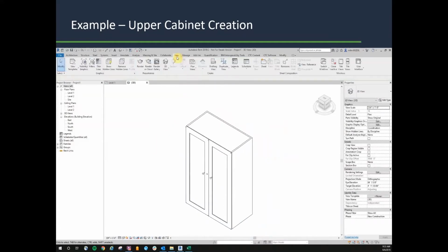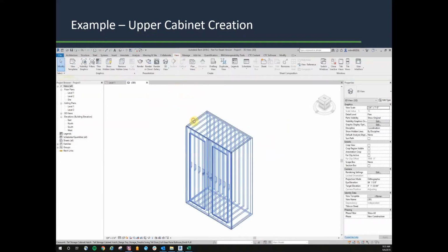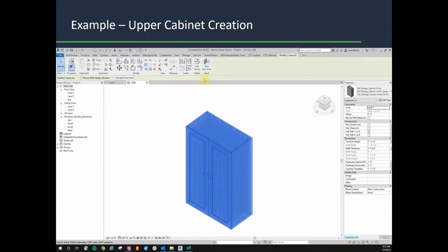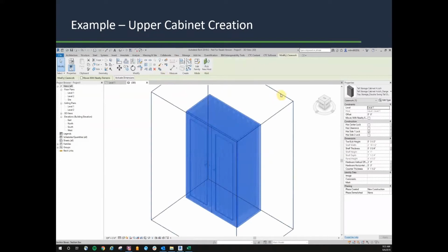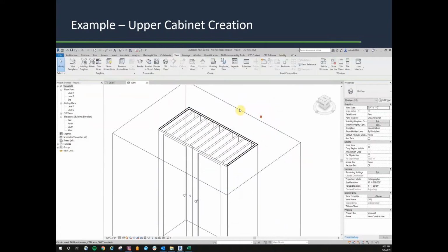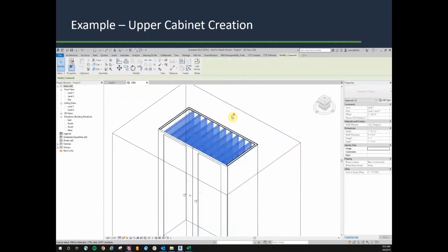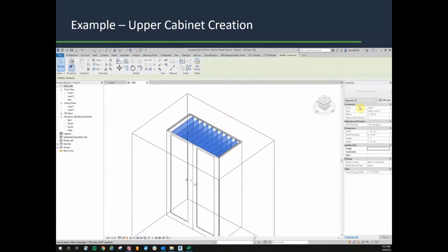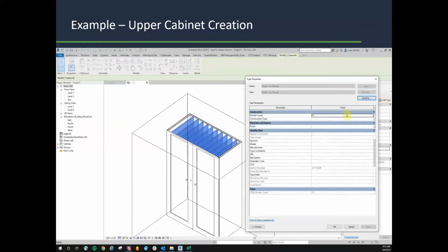So for this example, I'm going to create a 3D section. And I'm going to pull it down so we can start to see what's inside here. So now you can clearly see the vertical oriented shelving that we've added. Now I selected that independently. I just used tab select, and you can see right here that family is indicating the divider count of that nested family.